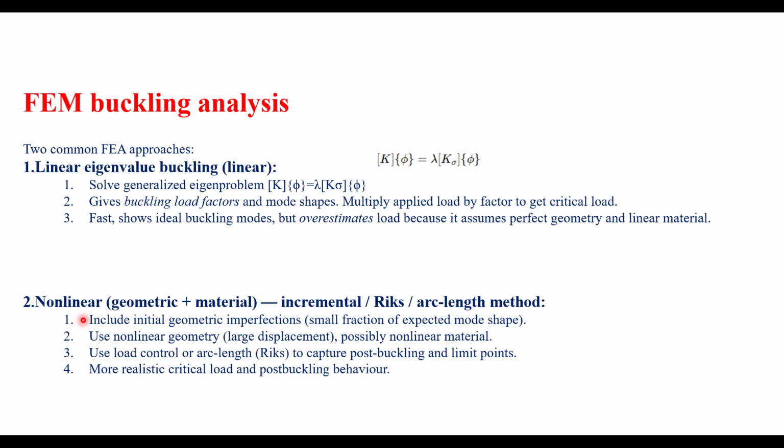Next, what exactly do we do in non-linear buckling? In non-linear buckling, we take the geometry non-linearity into account. Let's say you already know about engineering stress versus true stress, right? If you go through that, you'll get to know what geometric non-linearity is. And then the material non-linearity also, the stress strain curve will be taken. Then with respect to the incremental and arc length methods, these are the methods we use to extract the nonlinear buckling.